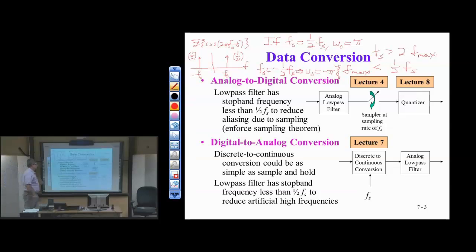All right, so as we talked before, we have frequency content really at all frequencies because of at least thermal noise, the random motion of electrons due to temperature. So no matter what sampling rate we choose, we're going to have aliasing. And so it's up to the design of this analog low-pass filter prior to sampling that will help us control the amount of aliasing that happens.